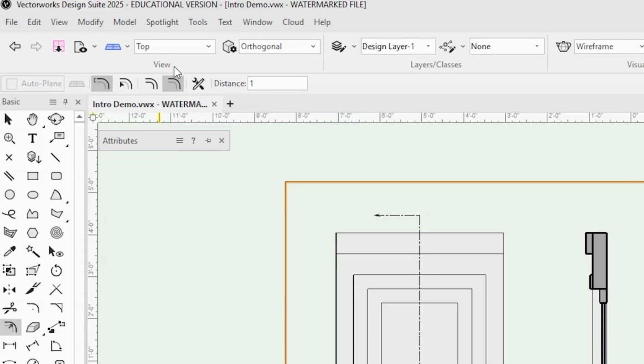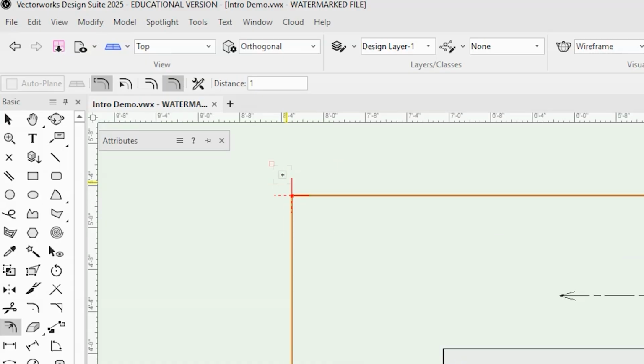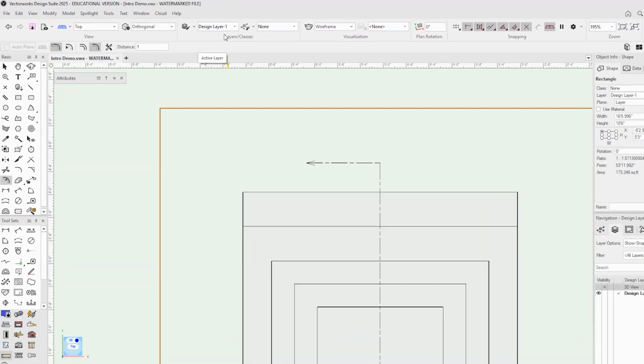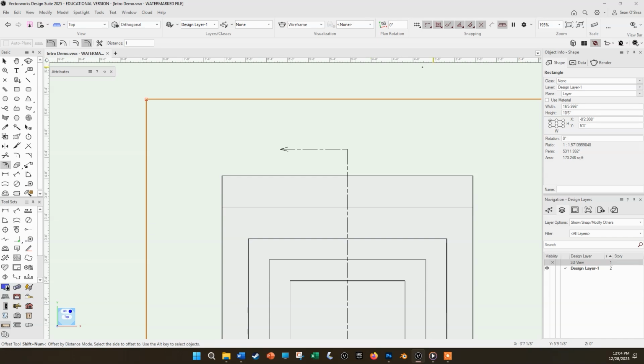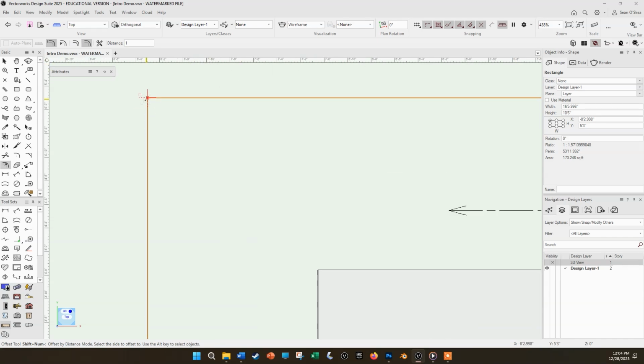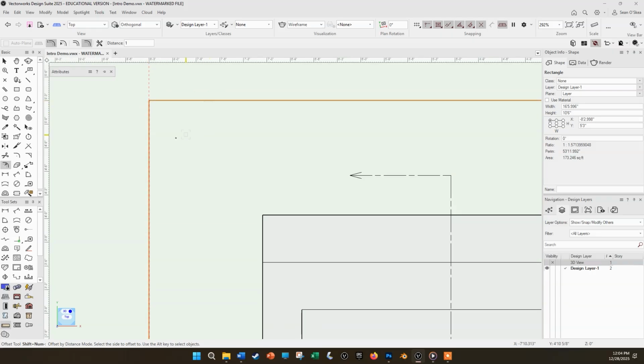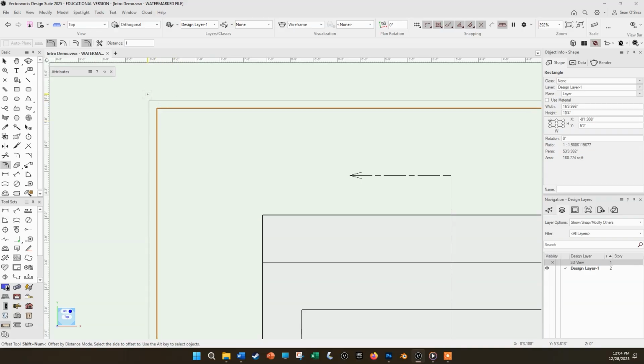Now remember that we're drawing on the design layer in this example here, and so we're still in the 1 inch to the foot scale. So shrinking the border by 1 inch in scale, we'll just move it a tiny bit, like 3/32 of an inch in real world scale on the paper. But this way we can see the border inset from the edge of the page, and we'll make sure that the printer or the PDF can draw the whole border. So if you haven't already, just click in the inside of the border to shrink it that tiny bit.